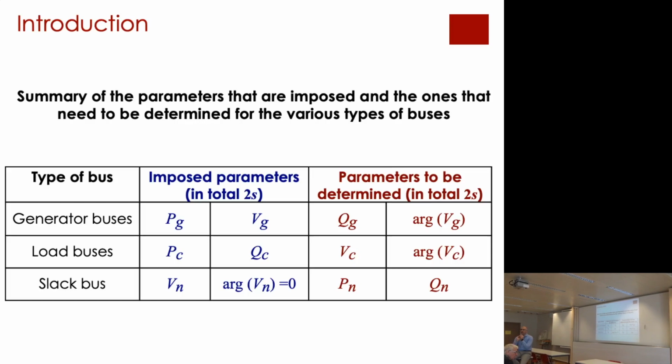So each layer of the power grid, let's say low voltage distribution, medium voltage distribution, sub-transmission and transmission grids, has equipment that can operate in a very restricted band of voltage. That's why you fix the voltage, and that's why normally when you solve the load flow problem, this V is the rated value of the voltage in that part of the grid. Normally you tend to fix it to the rated value of the voltage. And the VI star is the same. Yeah, correct.